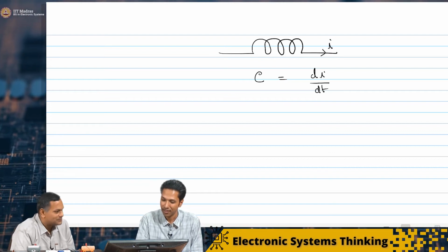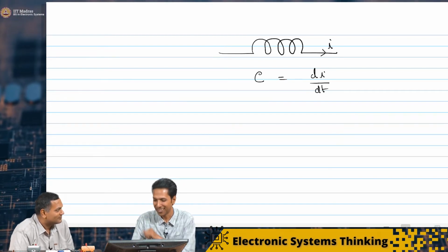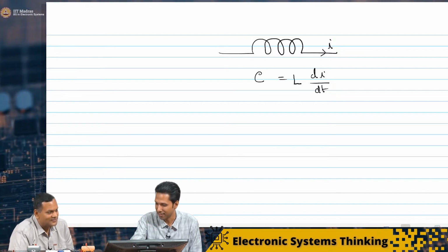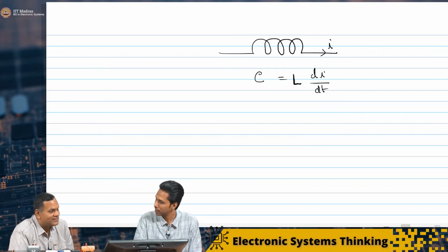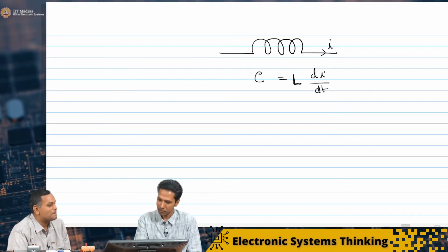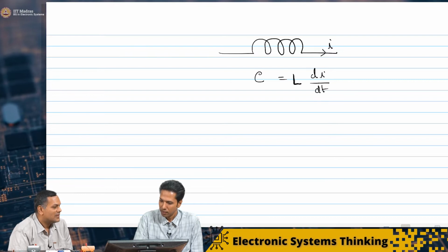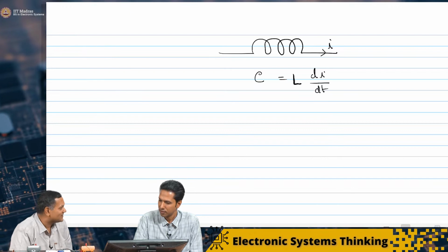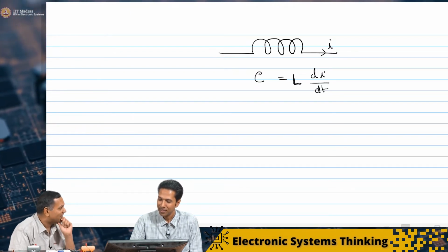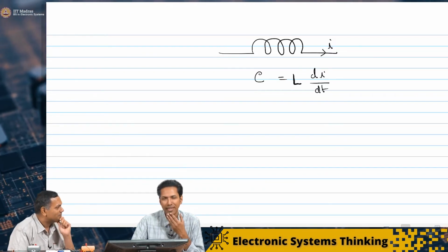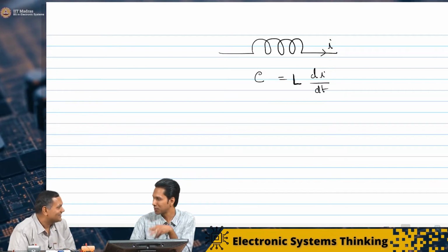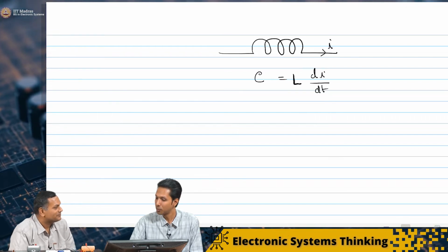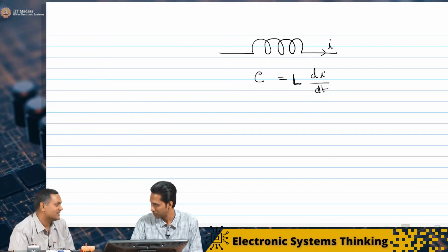Like in the capacitor, in this case there is going to be a constant called inductor, L. So L stands for the inductance. And what are the signs of this induced voltage? We must be following some convention, right? You may know Lenz's Law. Yes, it opposes the very cause that produces it. That is correct. So it will be minus L di by dt.